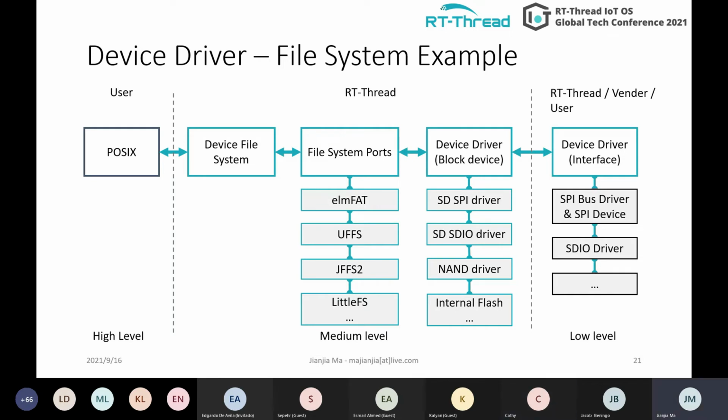In fact, in the RTThread, most of the common drivers are already implemented for popular MCUs such as STM and NXP and a few others. So probably you don't need to do anything, just tick the box and the file system will run.